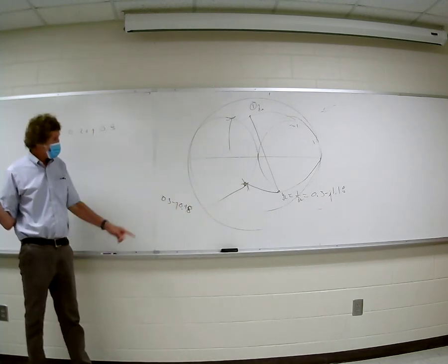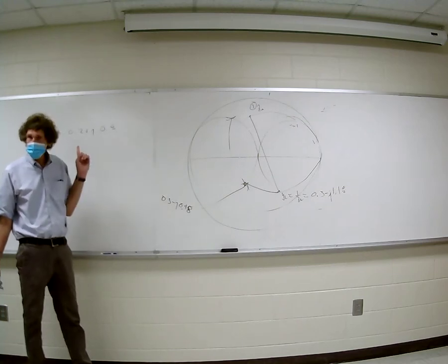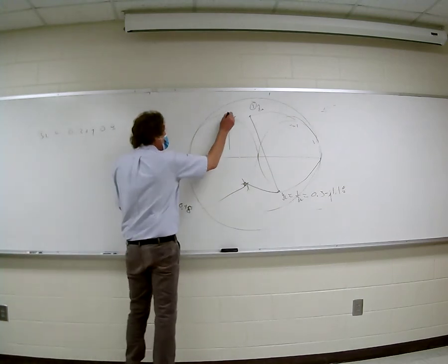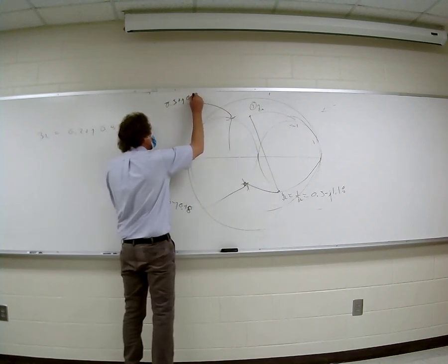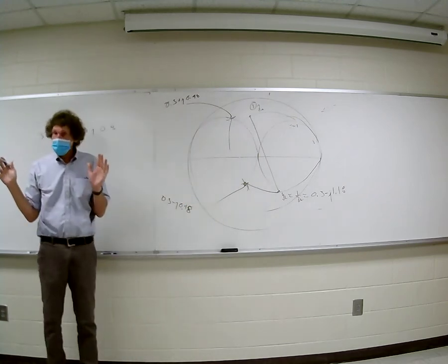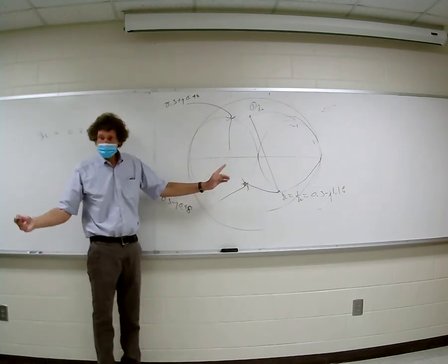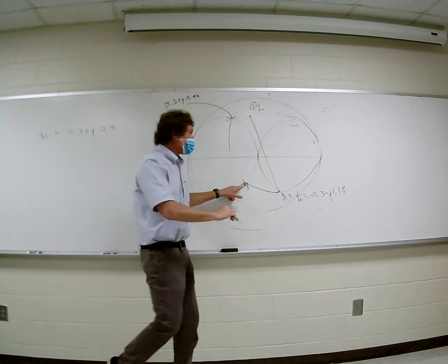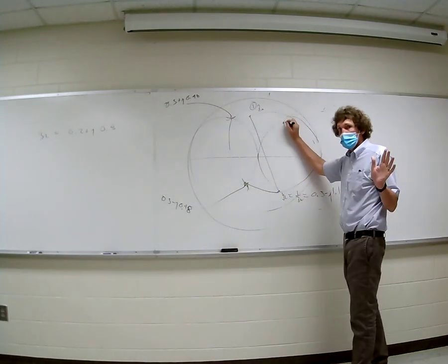All right, that's one of them. The conjugate point is going to be the same real part, 0.3, but it'll be plus j0.48, right? So the conjugate point up here will be 0.3 plus j0.48. Remember, that's admittance, right? Now, here's where you think ahead. If I add something in parallel to get to here, then when I go from the admittance to the impedance domain, I'm here, right? Y'all hear me on this?